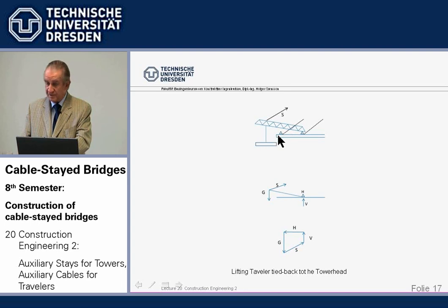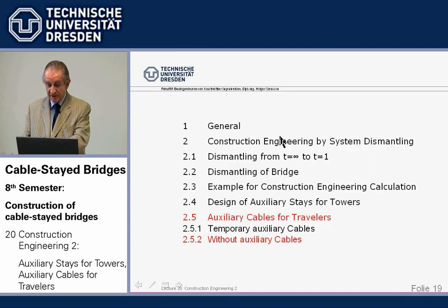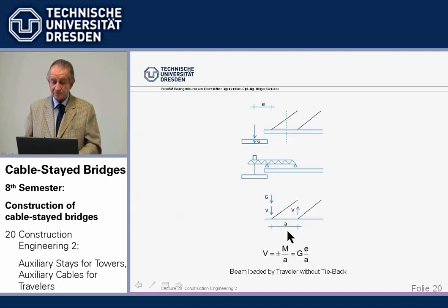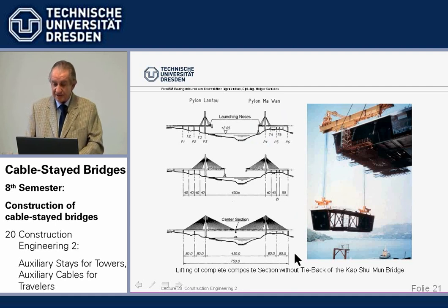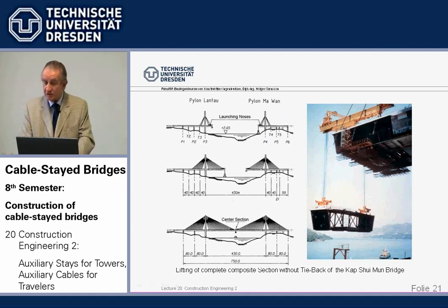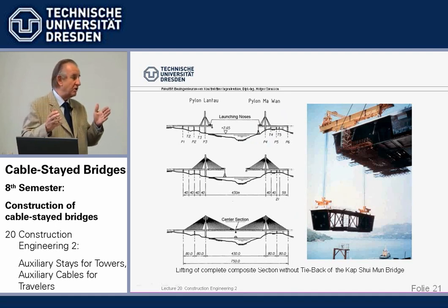Here we've lifted it off from the front support, then we leave it on, and then of course we have the weight plus the moment from the eccentricity, which is an important force, and that can only work if I have a deep beam and or a small cable distance or element length.